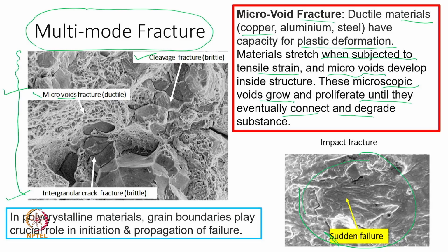That is what we call a crater, and that has also been observed a number of times on the fractured surface. So, we want to differentiate: there is a micro void, there is a dimple, there is a crater. Maybe the magnitude or size will differ, and material properties will differ to some extreme.